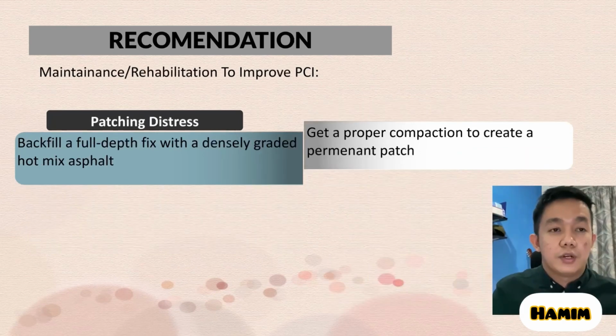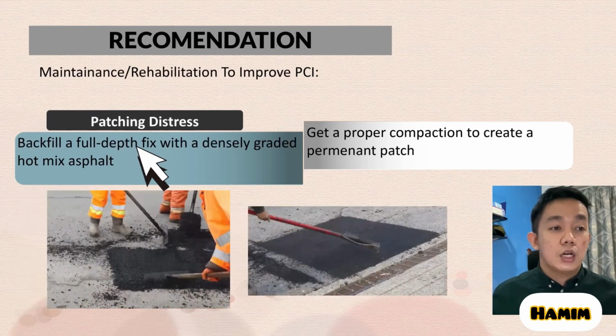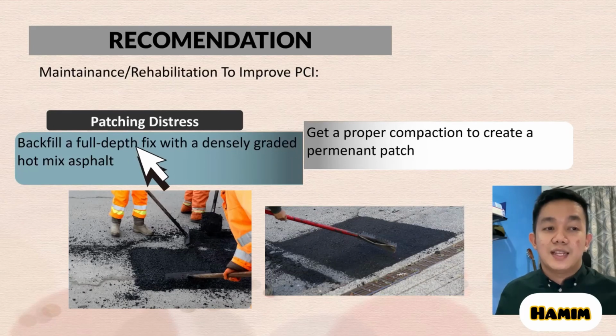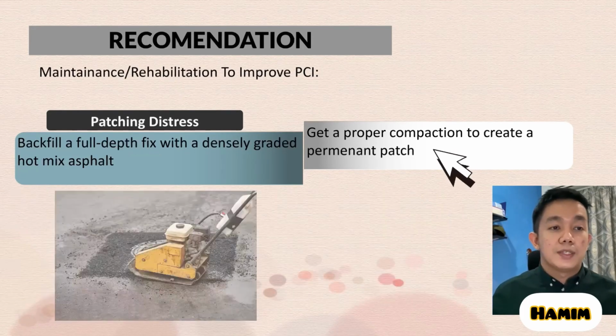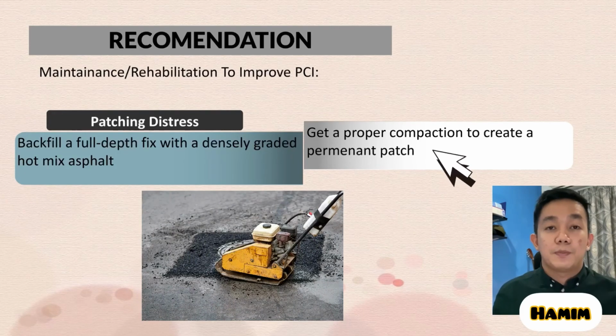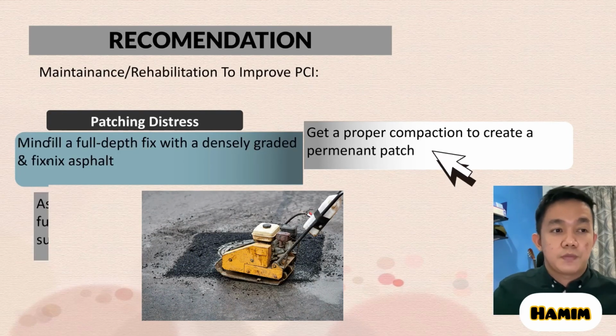The third recommendation is that we must patch the pothole. Patching distress is a backfill of full-depth fix with densely graded hot mix asphalt. Other than that, we must get proper compaction to create a permanent patch.